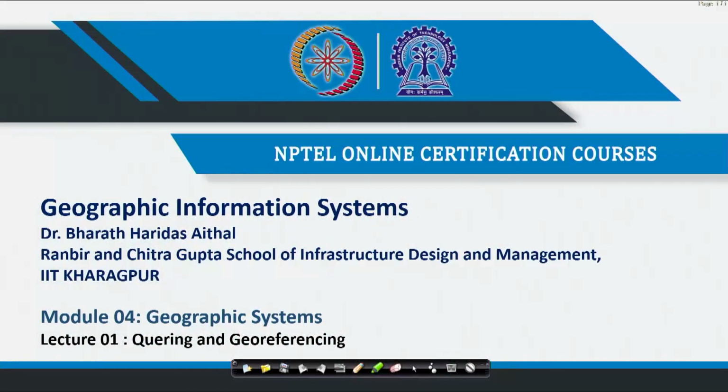Namaste. I'm back with the next set of modules, wherein we would start with looking at how we do querying, how we look at georeferencing. Georeferencing is to tell you which portion of the Earth's surface a particular picture belongs to, which means I'm trying to tie the coordinates, tie the map, to a certain part of the Earth's surface. As soon as you click on the map, it has to say where it actually belongs, using a certain reference system.